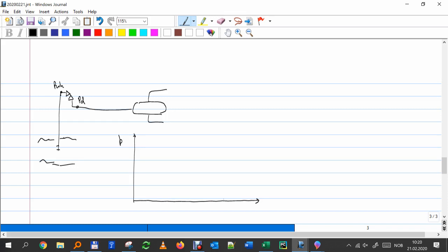So it was pressure versus Q of the gas, right? And how will the PWH look like? How does the curve look like? Available pressure at the wellhead. You already forgot? If you forget, it's similar to, I have to go from PR to PWF, that's the IPR. You always remember how the IPR looks like. And then the pressure here will be like an IPR, but shrunk. I will have less pressure available there. So the curve is like that.